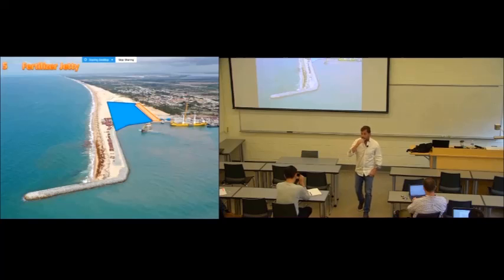I was thinking you can actually do a modal analysis. Yes, you can. If you write the software with the variable frequency, you can see how the pile moves, and then how it goes higher and faster, but it's not too much movement. So you can determine what is the worst frequency if it hits this pile.